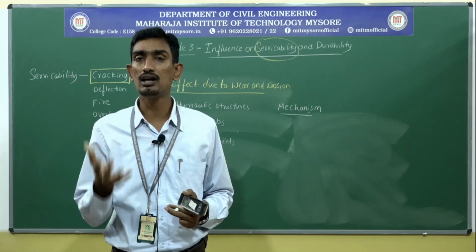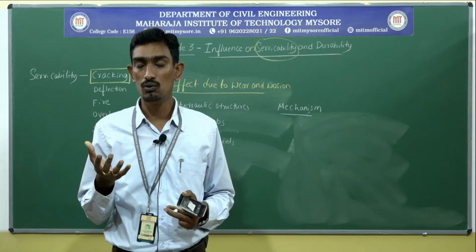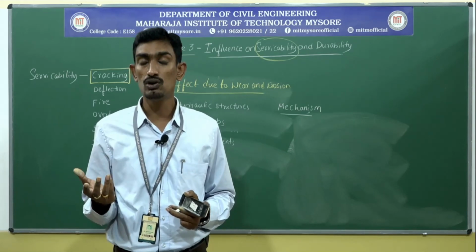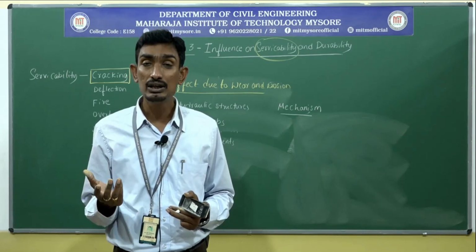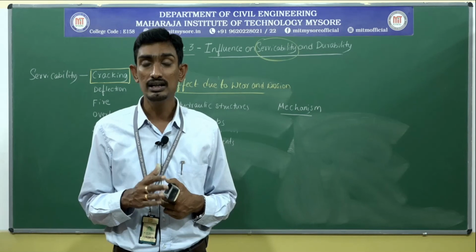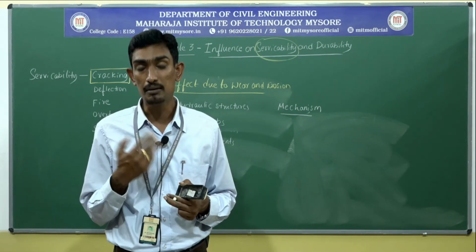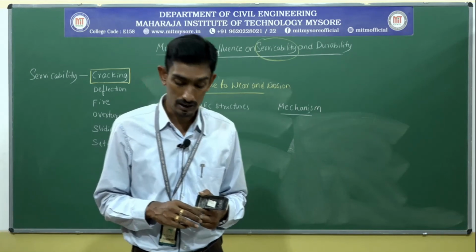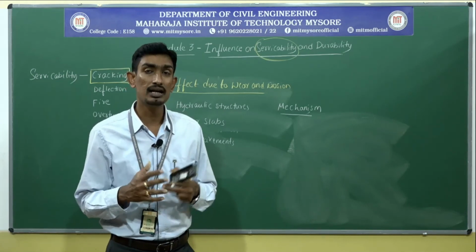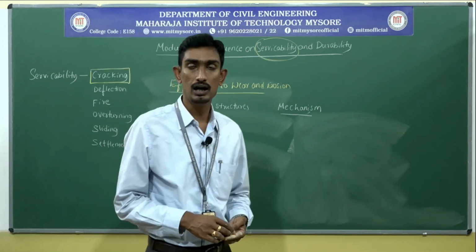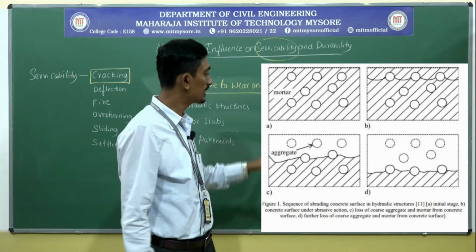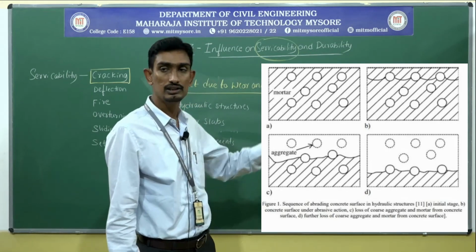Because of the development of eddy current inside the water, the riprap or debris, the construction trash left, will tend to create an erosion or abrasion action on the concrete surface, which will finally lead to damages or cracks on the concrete structural element. Now how exactly is this mechanism going to happen? We can see clearly from the photo how exactly the mechanism happens.